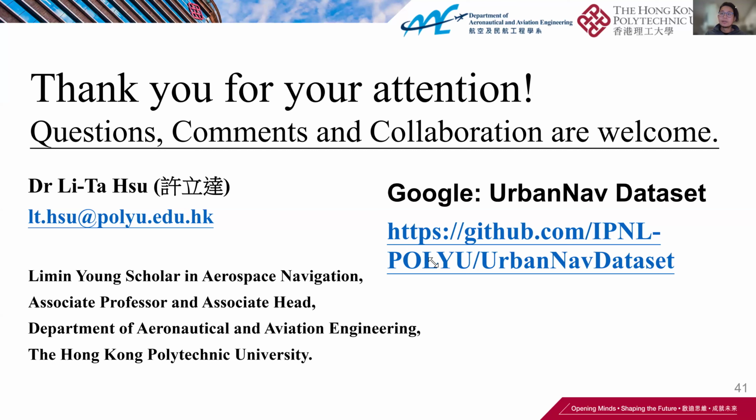Oh, yes. Those KITTI and Waymo datasets don't really provide the raw level, which means the pseudorange, carrier phase, and carrier-to-noise ratio level of GNSS measurements. They usually just give a point, which is the NMEA solution. Because I'm coming from the GNSS community, I would love to share this: those robotics people didn't focus on it as much as we do here at ION. So that's the difference. Also, for the KITTI dataset, the environment is really suburban. It's quite a simple dataset.